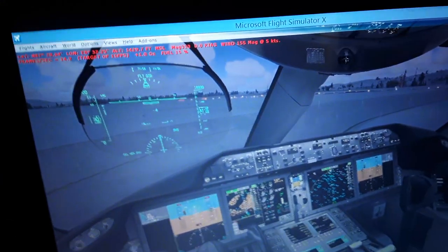Also the instrument landing system transmits radio frequency from the threshold runway antennas, and it is received by the onboard antennas of the aircraft. It helps us align with the magnetic heading of 130 degrees of this specific runway, and also the localizer heading and localizer radio frequency. We have to tune either manually or automatically. Also, it's going to give us the vertical glide slope.